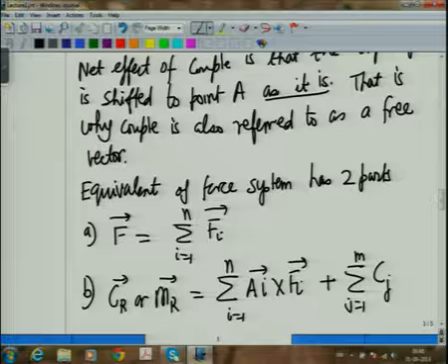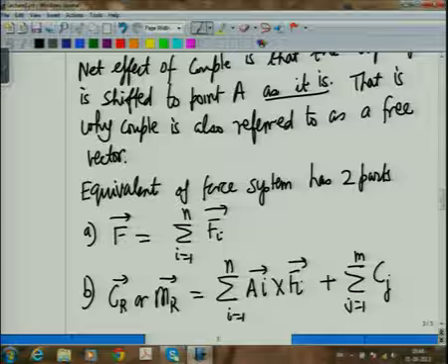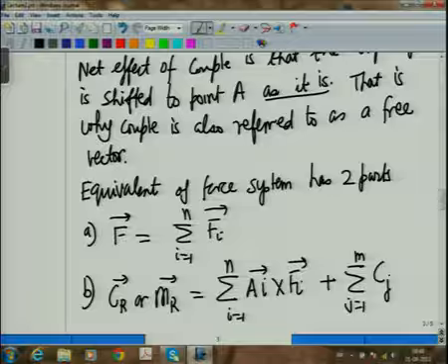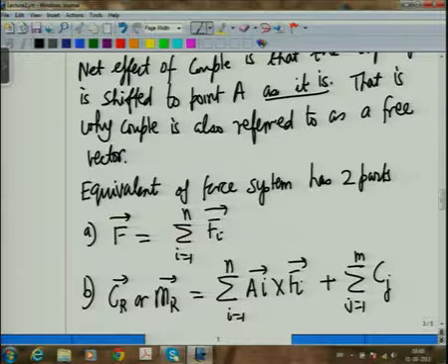But then mathematically, if you look at it, by making it simplest, we have not really mathematically reduced our problem. Why? Because the simplest resultant, with that, you have to say which point it is. When we do it like this, it could be any point. But when we talk of a simplest resultant, then the freedom to choose the point goes away. It has to be a particular point or a particular line. Is that clear? Okay. So now let's try to see how do we find the simplest resultant of these systems.